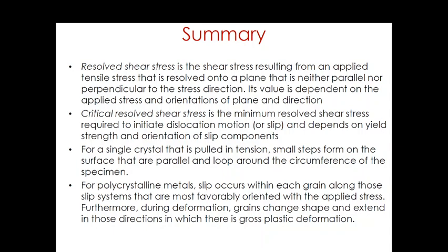For a single crystal that is pulled in tension, small steps form on the surface that are parallel and loop around the circumference of the specimen. That we have seen in the case of the single crystal zinc sample. For polycrystalline metals, slip occurs within each grain along the slip systems that are most favorably oriented with the applied stress.